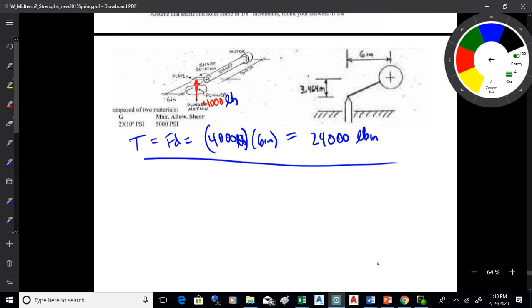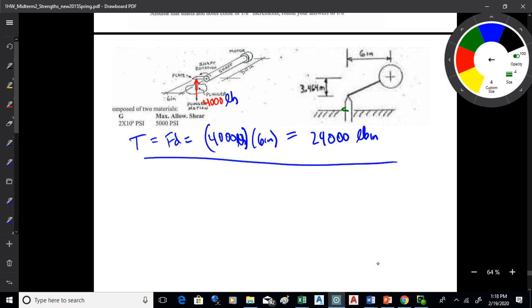You're going to have a bearing in there of some type, right, to hold that plunger in? I mean, you just can't be pushing on something like that. Something's got to hold it in place. And I'm not talking about just the downward movement. It's the movement to the side. Because if you just pushed on that thing, as shown, you'd push the plunger to the right, wouldn't you? With me there? But so you need some sort of bearing in there to hold it. Because if you don't, that whole plunger will get pushed that way.